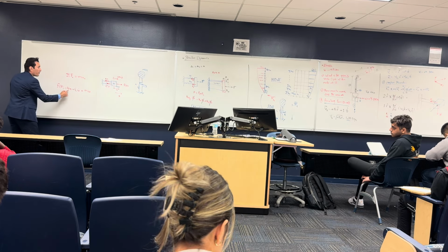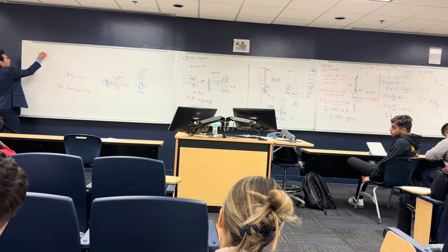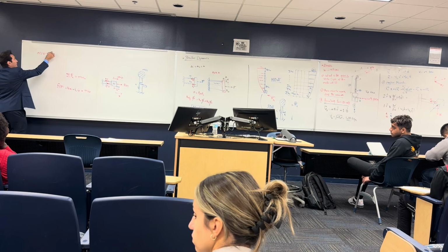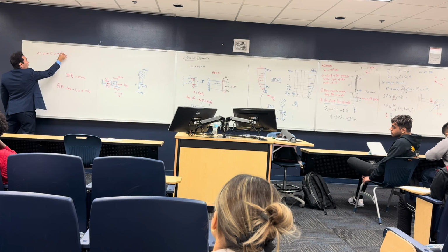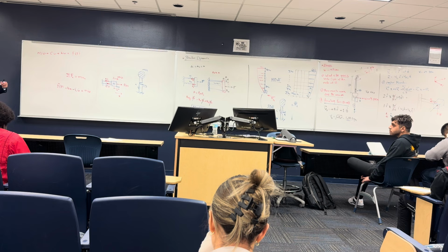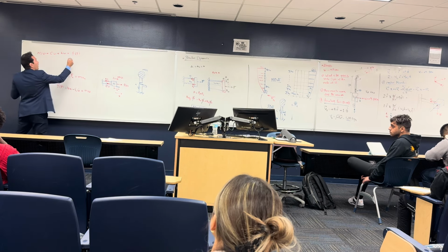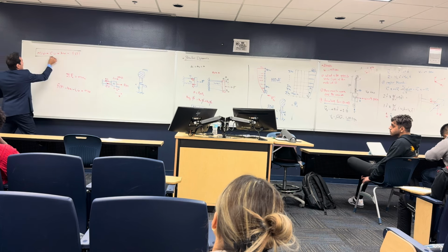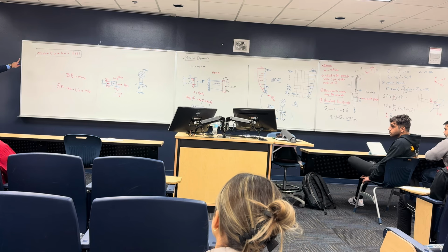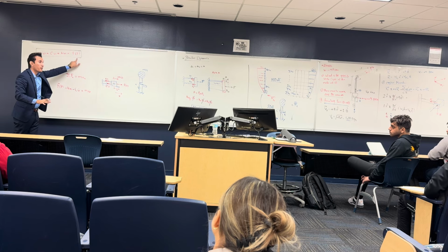Right, so what I'm gonna do, I'm gonna send these two to the other side, so I will end up with m u double dot, and both of them positive, c u dot plus k u is equal to F(t). This is a very, very important equation in the world of structural dynamics. You're gonna do your BE exam after many years. This is very, very important when we solve the structure. All right, so this equation has a mass, has damping, has a stiffness, and has an earthquake force.